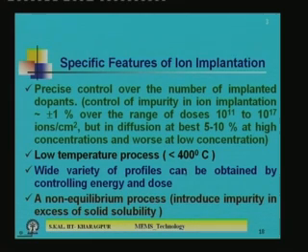And nowadays in all VLSI processes people prefer low temperature because of the out diffusion of impurity, because of the problem of rearrangement of dopant atoms, and further diffusion which will change the doping profile, which people try to get rid of. As a result, a low temperature process is highly desirable, and ion implantation is one of the choicest methods of incorporation of impurity atoms into the silicon.